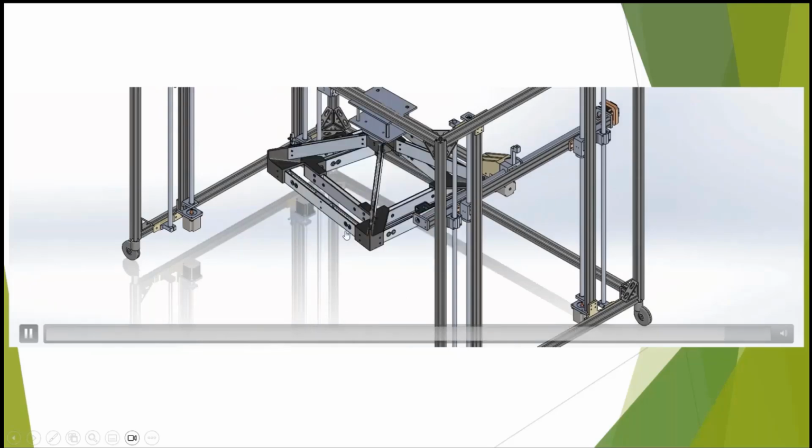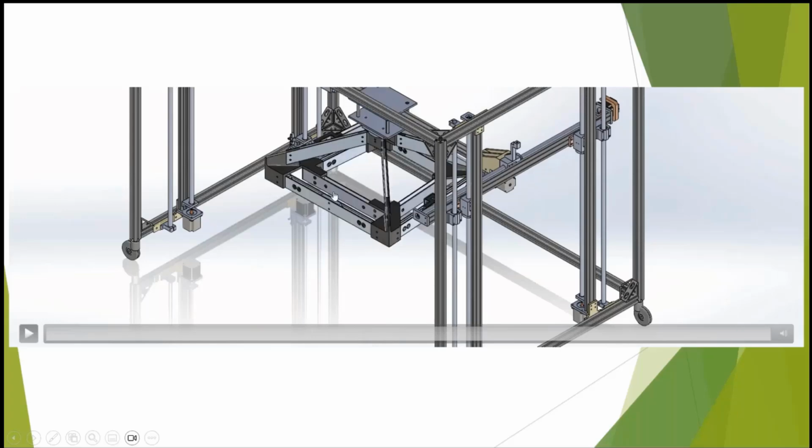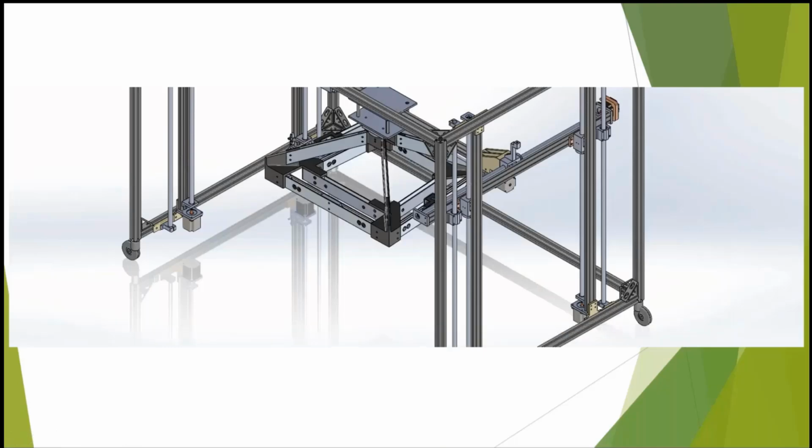The nozzle is basically the head, whether it is for any section, the hollow column, formwork for short span, or the blocks. It's two rings and it has heat elements inside. The cavity allows you to pass reinforcement, and you can make any kind of nozzle shape. With the movement, the UHPC is deposited between the rings. That's why some people call it slip forming, which is fine, but it's the automation of the process.